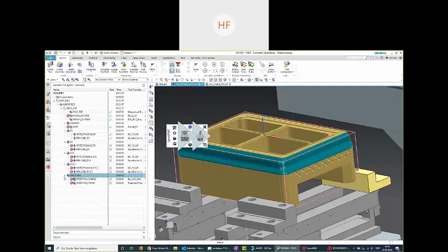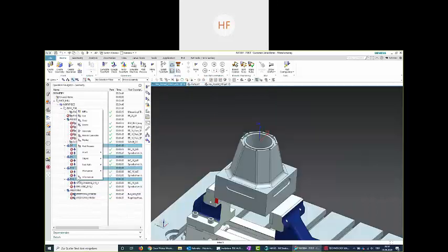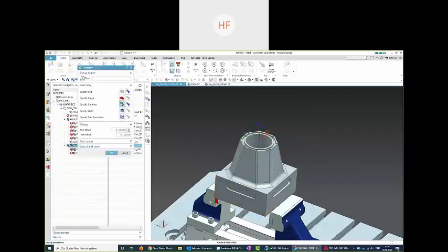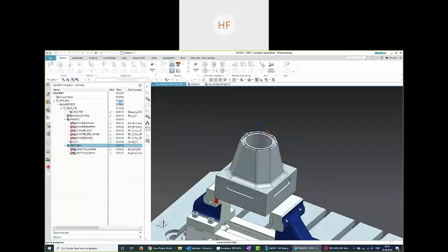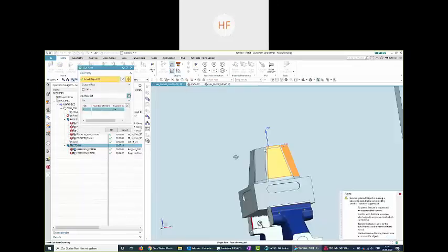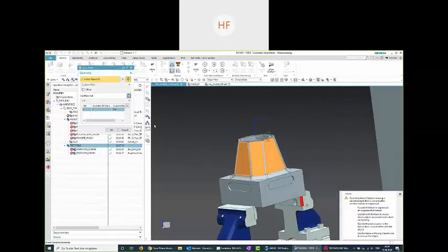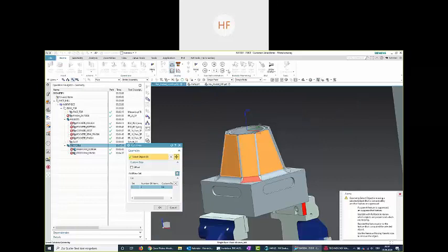Here we go. So now I do have some drilling operations left, like the diameter 8, 6, 10, and the second 10 diameter. Just make a right click on it, delete, gone. Let's return to the freeform. I have to specify the cut area once more, but we remember that by using the replacement assistant, I already have reassigned 3 of them. I need those other faces as well.